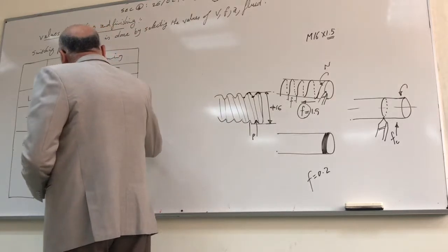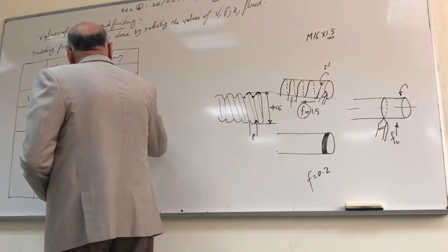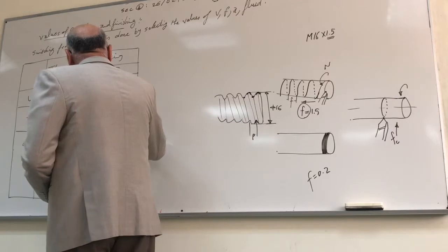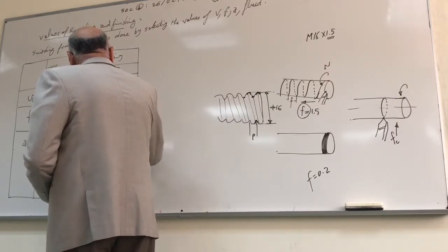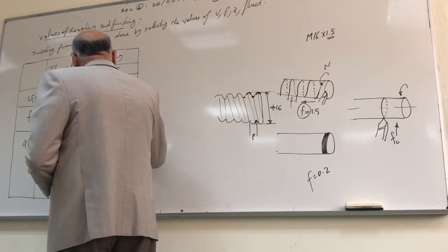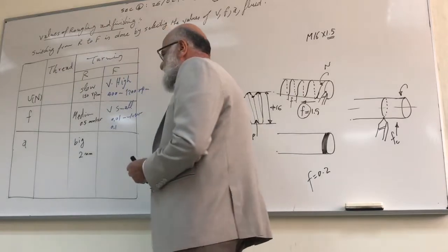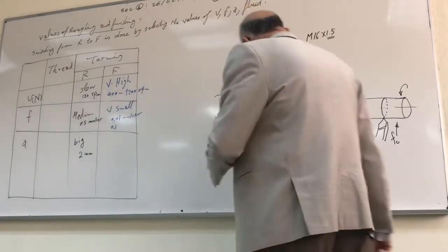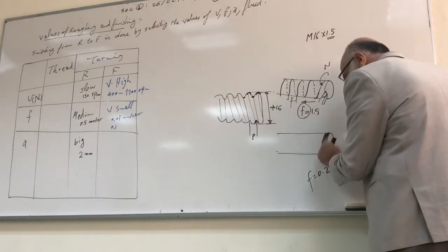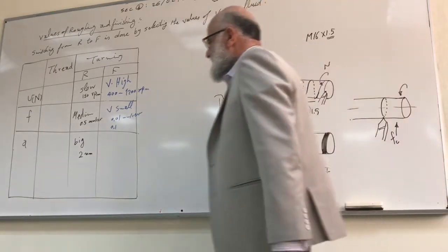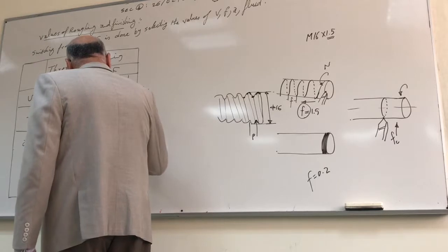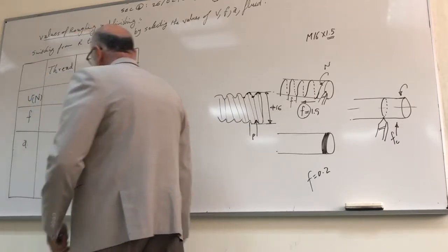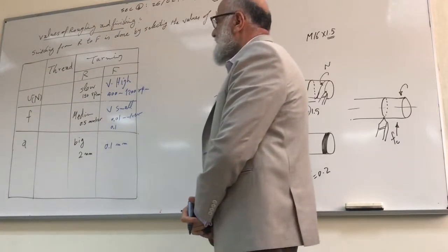About the feed, a very little, very small value, 0.01 millimeter per revolution, maximum 0.08 or 0.1 millimeter per revolution. Very little. Look here, very little. Depth of cut is also very little, about 0.1 millimeter or less.